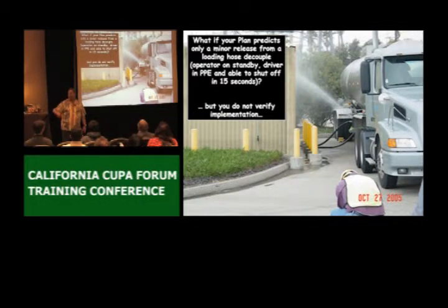Well, maybe they didn't follow the proper procedure, maybe they didn't wear the proper personal protection equipment. They're not able to implement their active measures. This is where I really would have preferred a safe drain or some other provision to contain that, even something that's not going to certainly hold the volume of the tank, but something that'll help so that somebody can respond, shut the flow off, and it still retains it, because this guy didn't stand in the right spot to shut that off.